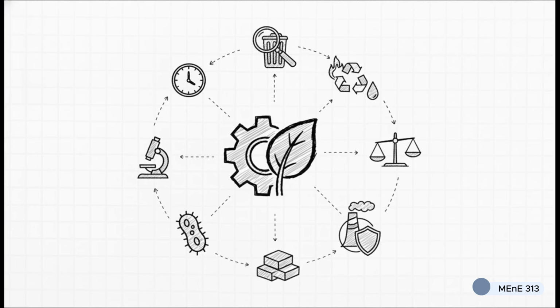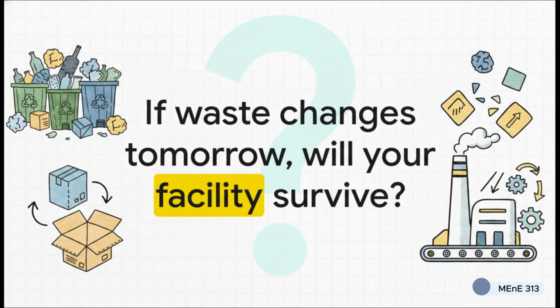6. Biodegradability points straight to biological digestion. 7. Chlorine and sulfur dictate your acid-gas controls. 8. Ash content drives your entire residue management system. 9. Refuse-derived fuel still requires intense consistency testing. And 10. Supply stability. Knowing for sure you have the right waste for the next 20 years dictates your financial viability.